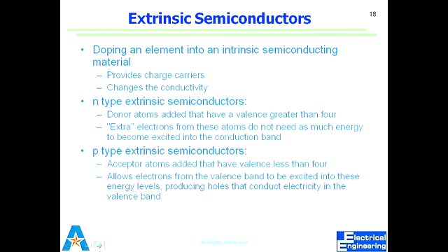There is a different concept for semiconductor materials called mobility. Mobility is important, not the conductivity. Conductivity is more relevant for metals, where we have the notion of Ohm's law: the more voltage we apply, the more current will flow. There's no similar thing for doping versus the semiconductor. If we dope them too hard, mobility goes down because of collisions with the lattice, the static atoms. Make sense?